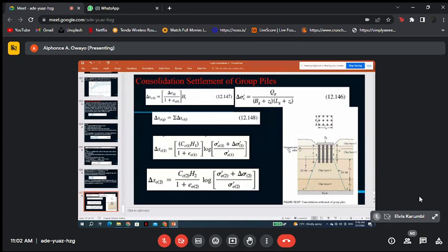So here you treat the pile dimension as if you would treat, for example, one rigid foundation. So you reduce the group to a section similar to that of a shallow foundation. Okay, so this is what you can see here. And then the increment in load is basically related to the pile load, from the formula that you can see.